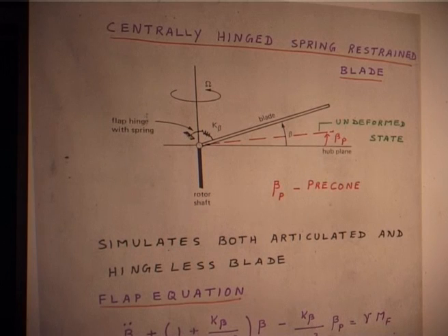I will not again derive the entire equation, please understand. That is why I said, once you get one equation, position vector, you rotate it again, get the acceleration, get the aerodynamic load. The only load I have added is a spring. Now, the spring will give a spring moment, which depends on how much the deformation is.